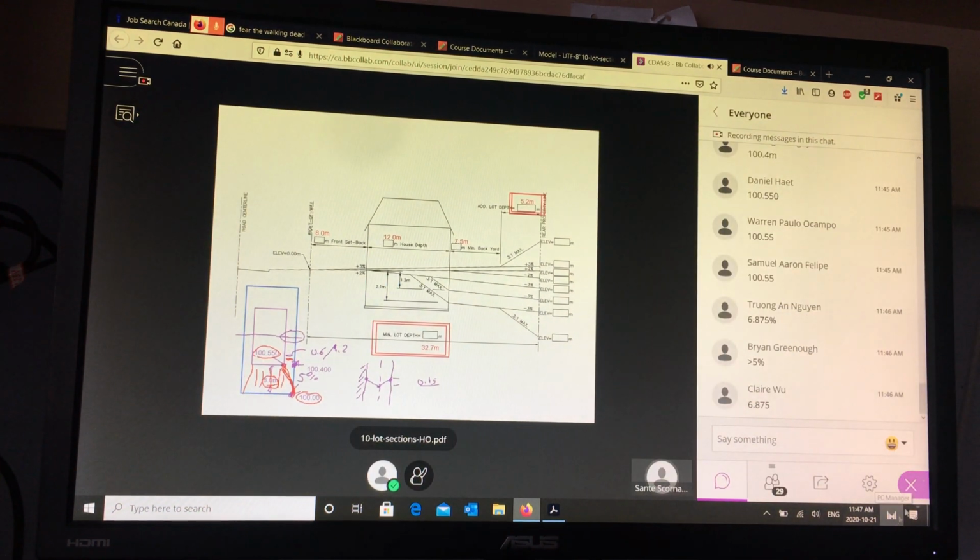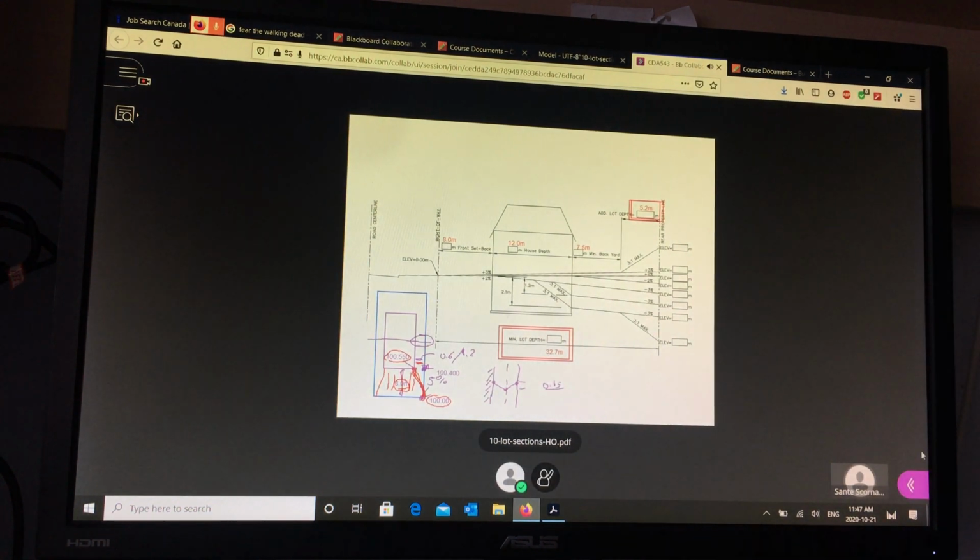That's my point here. If the architect wants to use a maximum of 5%, I have to use something flatter to get the elevation opposite the corner of the house along the side of the lot. So let's reverse engineer it. What if we go from 100 up to the house at 5%? So instead of using 5%, I'm going to use 0.4 over here.